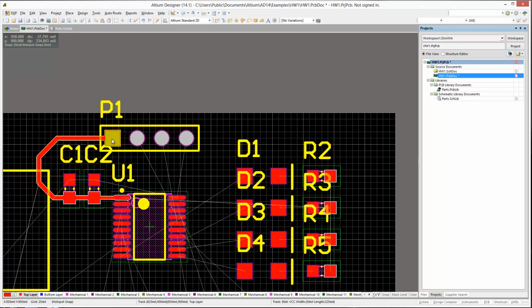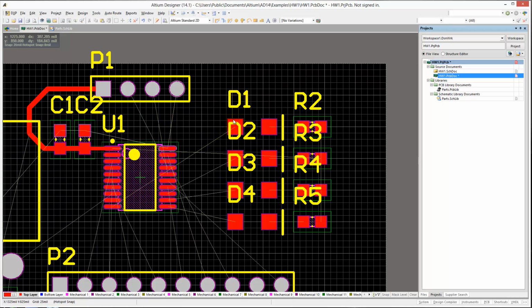So it will draw it from over here, there is inductance, and thus the voltage will actually drop. So we have to change our schematics and add a capacitor in here that will help these LEDs to not pull down the voltage too low and actually turn off our microcontroller.